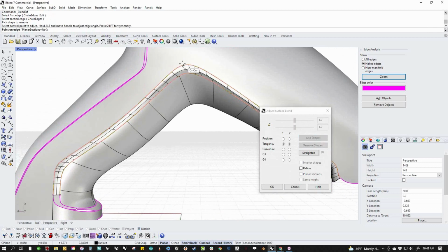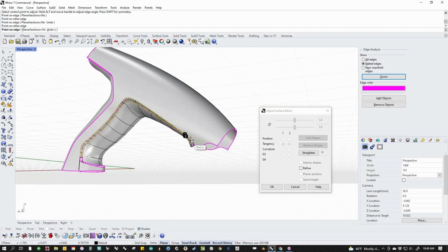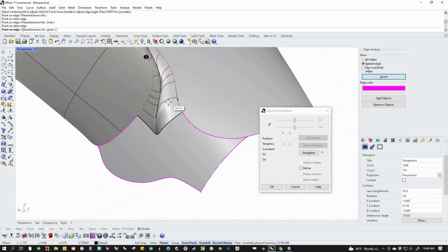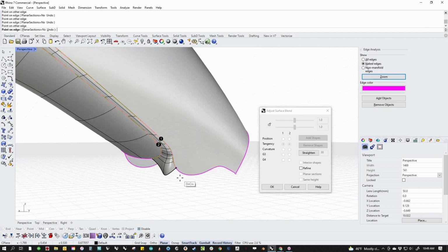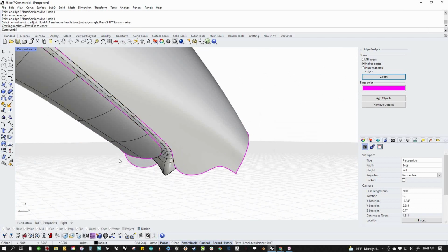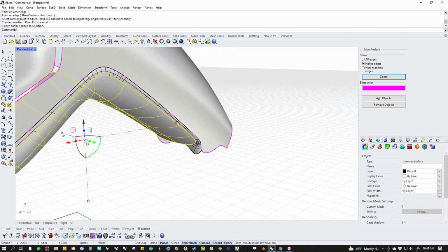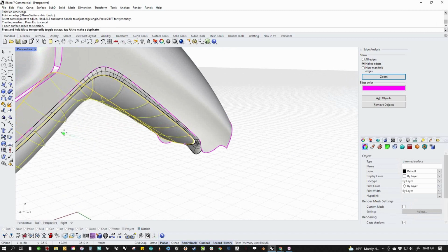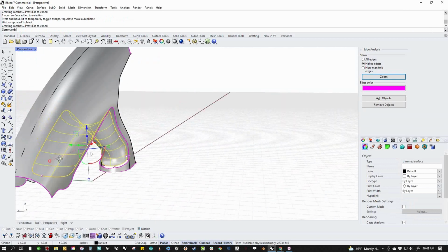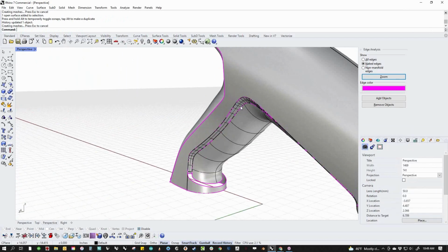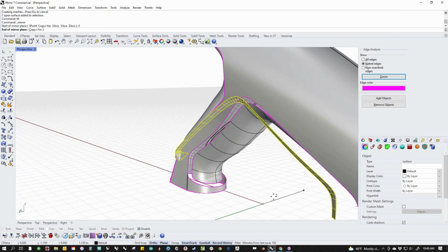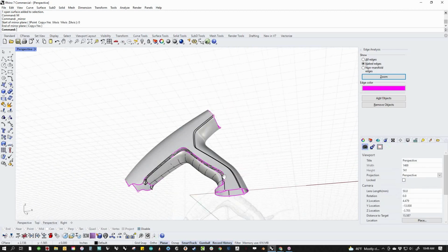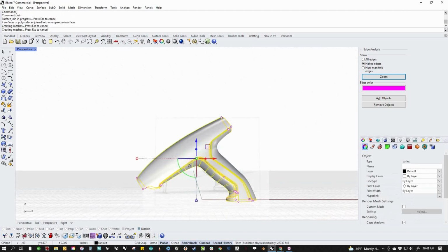And let's add a shape in this corner, because it looks like the isoparms are squirreling a little bit there, and I don't want them to do that. And because we did this with history, I have the option of editing this. And so I think I'm going to exercise that option, and I'm going to grab this and make this just a hair thinner, like that, just so that transition sticks out a little bit more. And then I switched sides, but it doesn't really matter because it's symmetrical, so we can just flip this over and we'll join it up and see how we're doing.